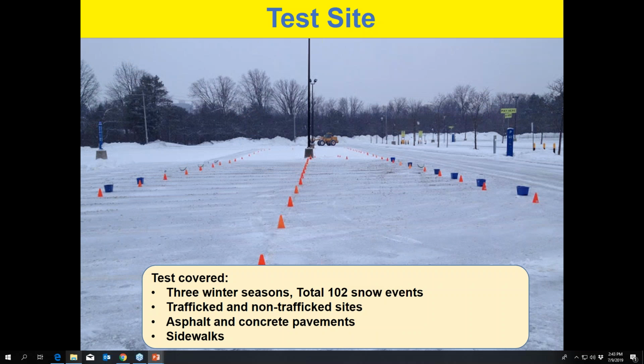During the test, we designed our test site so that some areas were trafficked and some were traffic controlled, to understand whether traffic has an effect on salt melting. We also covered asphalt pavement versus concrete pavement, and we also included pedestrian walkways in our test matrix.